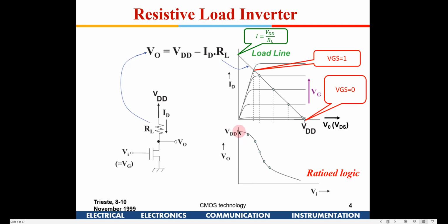But if I consider a case where Vin is equal to VDD, logic 1, so VGS is equal to 1. This is the voltage out here, the max voltage here. I should have written VDD here. I have worked a lot on 45 nanometer technology, so generally I get fixed to this 0 and 1 volt here. So this is the intersecting point, right? You will find that VOL is not 0 volt here, but it is more than 0 volt.